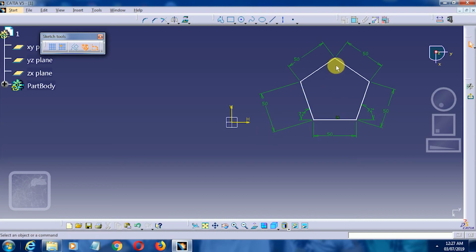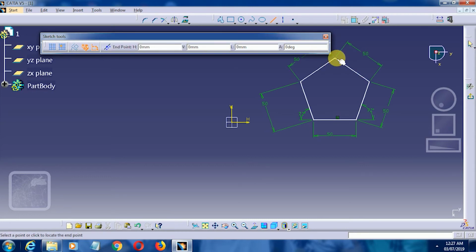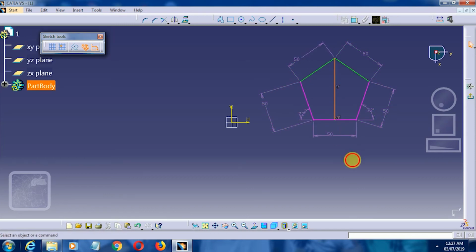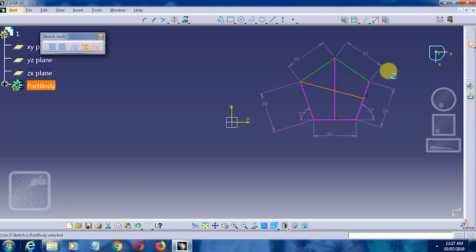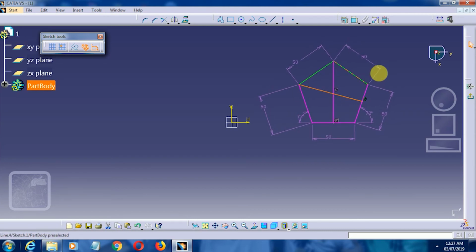So we will first of all connect this line with this very particular point by using a line constraint. Here we can see, I will click on the line, keep it blue because it represents verticality, then it represents the right side. Now clicking on the line, it becomes violet temporarily, but it doesn't matter because we are actually constraining it. Now if I select this point, both the lines become red, as we can see. So now I will go on this particular line and click on it. However, you can choose this line and this point, the point that is directly in front of the particular line.